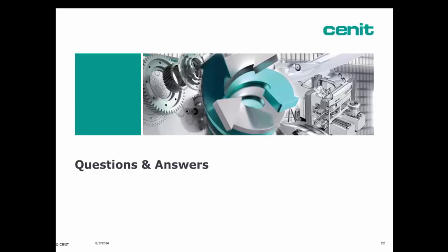And Sasha showed us as part of the demo the status change. So basically the conversion is triggered through a status change, and the files that are being generated, the lightweight geometry files, are checked into SAP, so they are stored within the same document info record as the CAD original, and can then be consumed by different participants, can be consumed by people who don't have the CAD tool, and can of course be used for further authoring on the basis of the visualization, so using SAP's authoring tool for the Visual Enterprise solution.